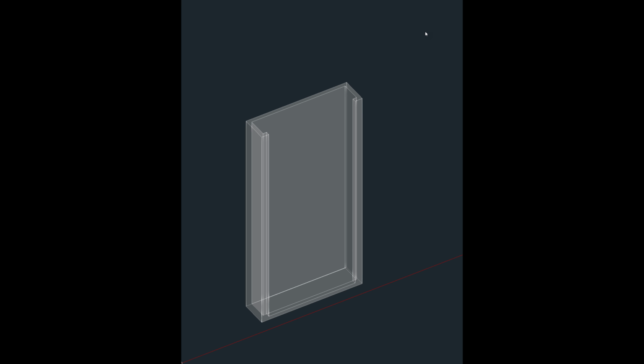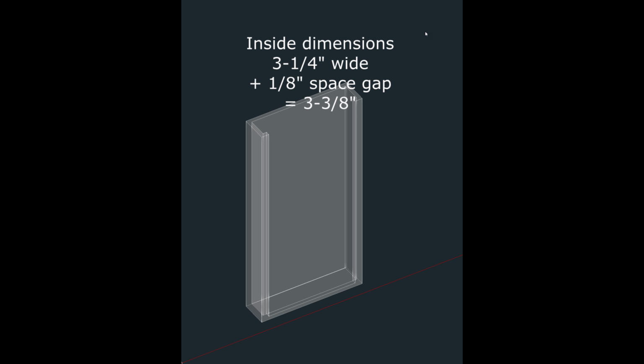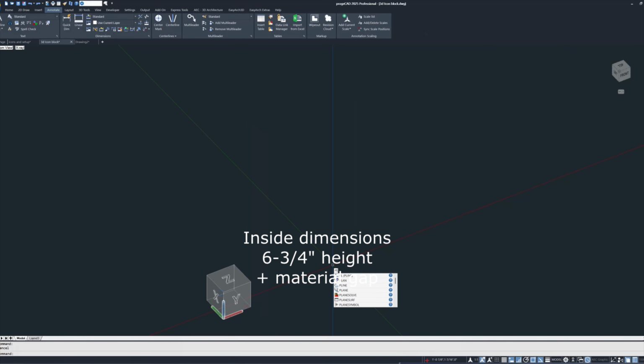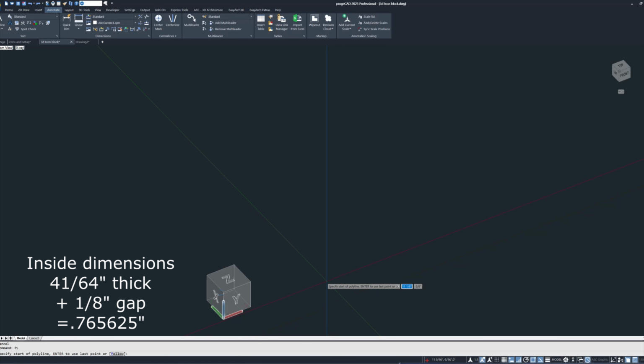Based on the X, Y, and Z box example we demonstrated previously, we can create a phone box by simply using a few commands: polyline, box, extrude, subtract, union. We rely a lot on our 3D drafting skills using these simple functions. Let's start out with the polyline command. PL is a shortcut key.